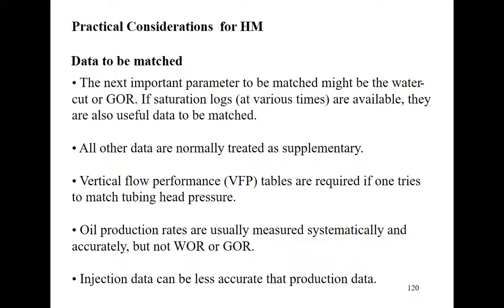So the next important parameter to be matched may be water cut and GOR. I already talked about that. Saturation logs, if available, we have to match them in the model. Mainly the water saturation log is also useful to be matched. All other data are normally treated as supplementary.